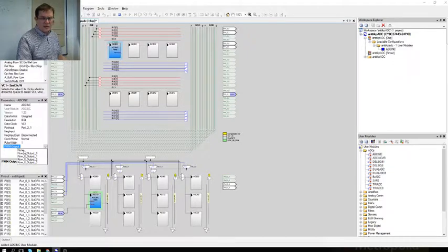You can actually also have the incremental value as pulse width out of the system, so that's also a digital signal. But in this case, we are not using it. I click just none. Okay, that's all you need to do for the A to D converter.